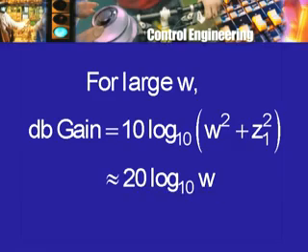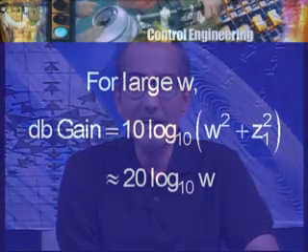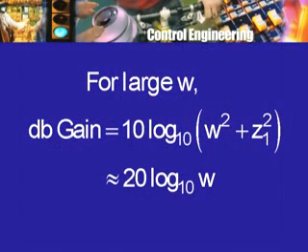Now, here is where one more example of engineering aptitude or approach comes in. If something is a function of log 10 of omega rather than omega directly, of course, I can always calculate log 10 of omega, I need a calculator or a log table. But why do not I consider log 10 of omega as the independent variable? That is, instead of frequency omega as so many radians per second corresponding to some practical frequency in hertz, why do not I think of log to the base 10 of omega as my independent variable? That is, instead of omega varying, I am varying log to the base 10 of omega. This was the idea that Bode used.